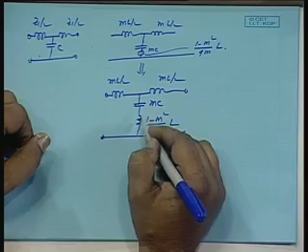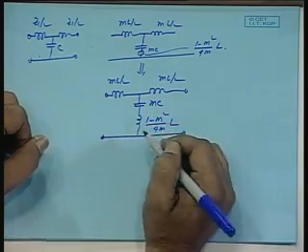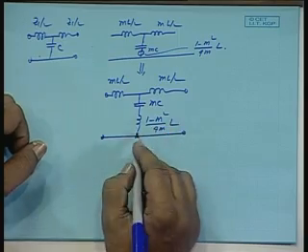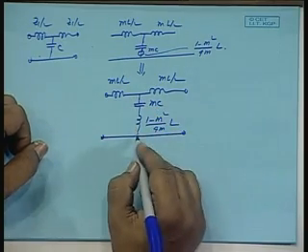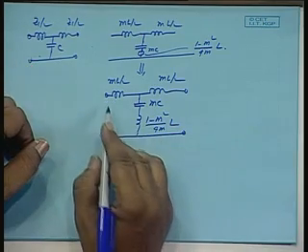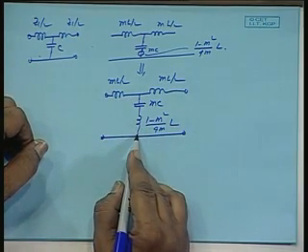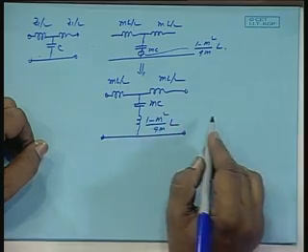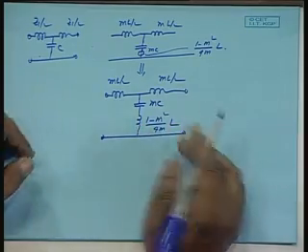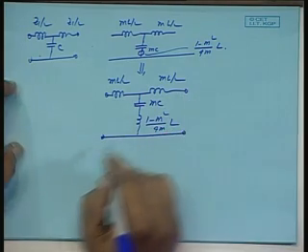It gives me a resonating element. This resonance frequency can be so adjusted that it becomes a short at that resonating frequency, okay, and at that time the entire signal gets shorted, there is no transmission.